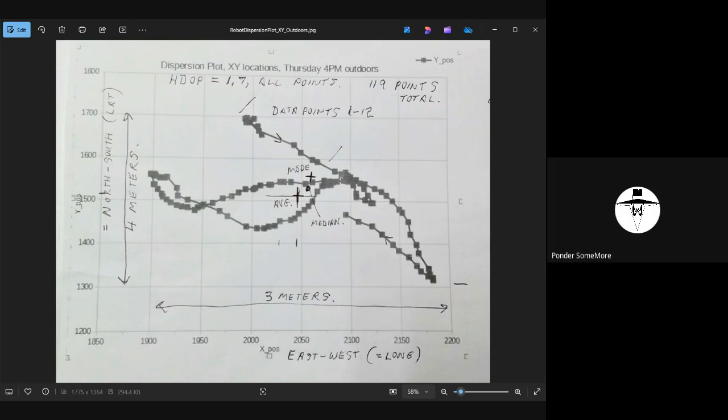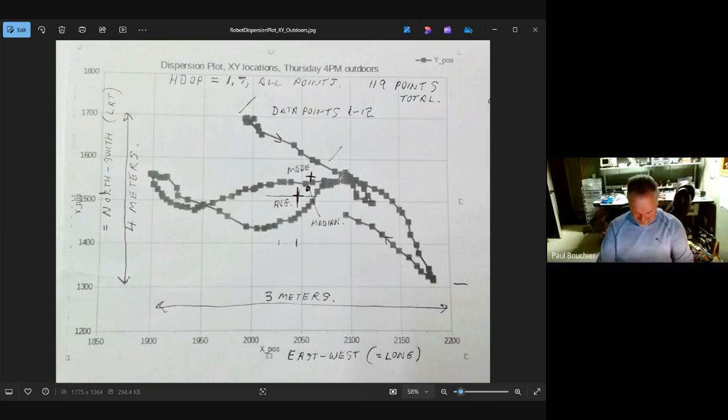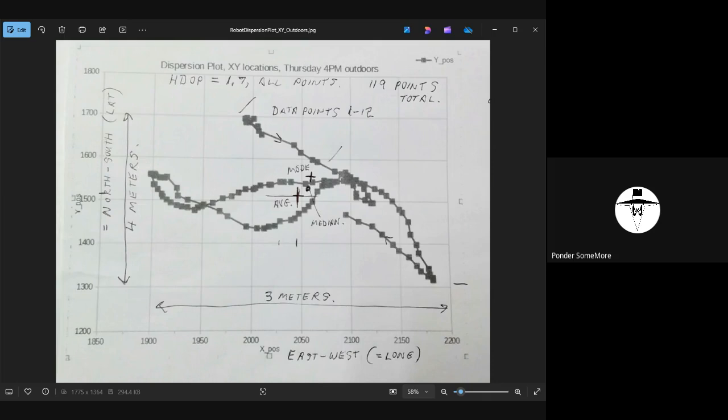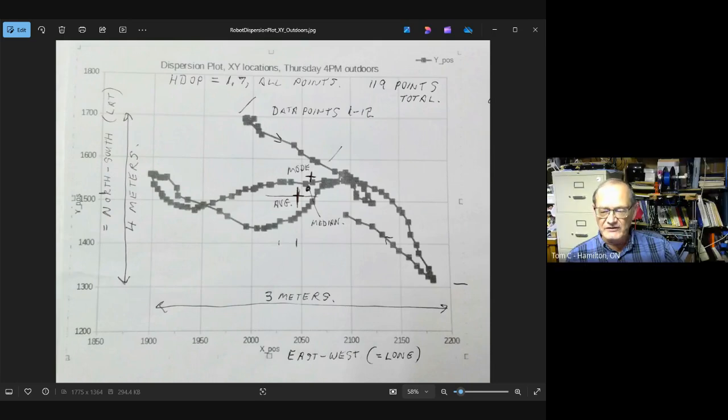That's basically the failure mode for my... I've had 2 of the F9P boards go bad on me over time. Ouch. Yeah, it hurts replacing those. And in both cases, it was the antenna power side that was failing, and all of a sudden it just couldn't pick up satellites. Wow. I have one of my 6Ms that's failed that way. The module itself that does the computations works fine, but the antenna doesn't work anymore.